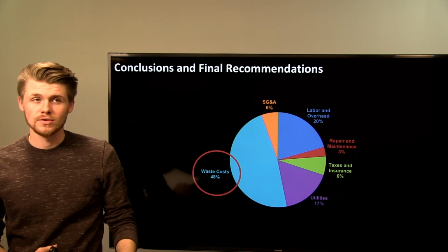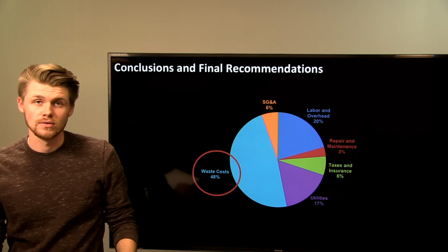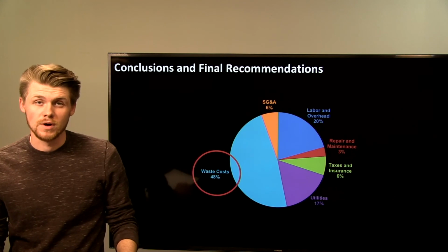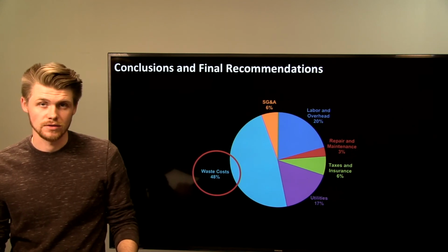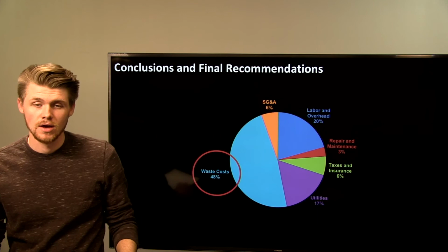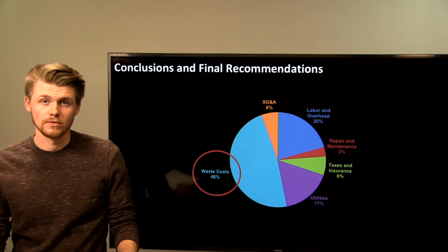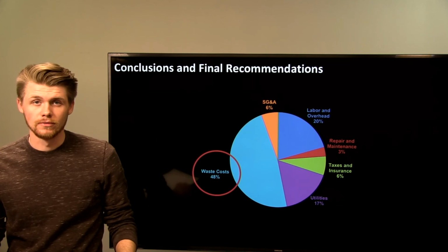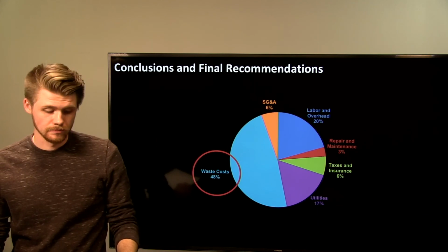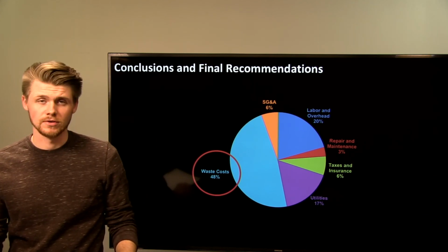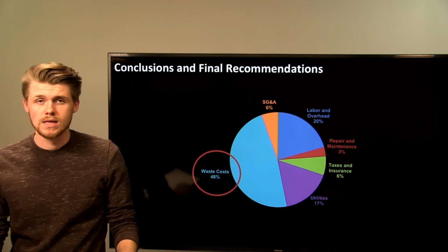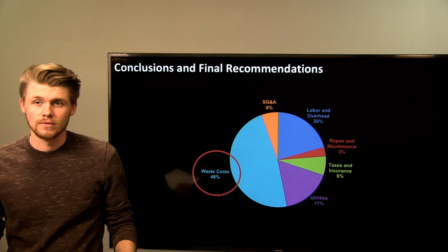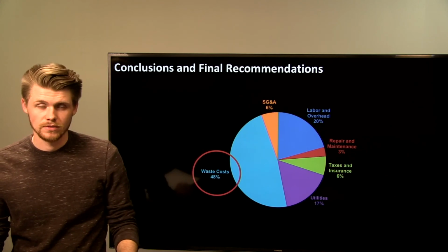Our main safety concerns are formaldehyde and H2. Formaldehyde at the concentrations that we have is above the lethal dose. So if any leaks happen, we really can't have too many people on the floor. If they're in that area of the plant, they're going to need full hazmat gear and an air respirator. The safety concern with H2 is pretty common sense. That's all about the flammability of it. Any leaks, open spark, if there's anything, nature's going to provide that spark, so we just have to be careful with that.